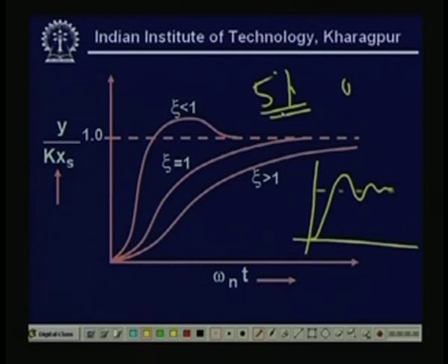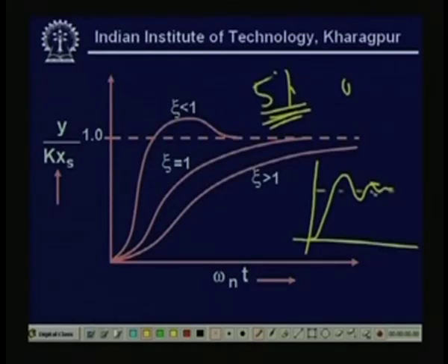Suppose the temperature is 31 degrees centigrade. I have to maintain exactly 31 degrees centigrade, or it might be only 30.5 to 31.5. If the temperature goes beyond that range, the cells will die. In that situation, I cannot allow this 5% tolerance band. But for many practical industrial processes like plants, fertilizers, petrochemicals, and steel, we can allow this 5%. That means when the output reaches 5% of the final steady state value, you take action. You take the reading, send it to the control valve, and decide whether it is to be opened or closed, or stop it, whatever the case may be.